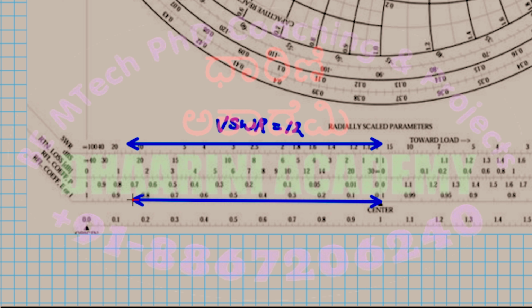I'm measuring over here. So I'll try to place it exactly like how I placed it. Its length will remain the same. Whatever length you got, it will be the same length, same to same. But the reading, whatever reading you get, should be somewhere here, corresponding to this point. So I think it is more than 0.8 but less than 0.9. Let me check. Okay, so that is the gamma, the reflection coefficient. Again, you will be able to measure only the magnitude. So let me take that as 0.85, somewhere in the middle, approximate. Proper one you measure later.